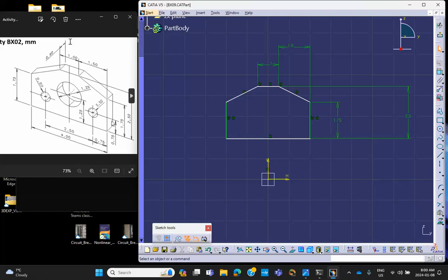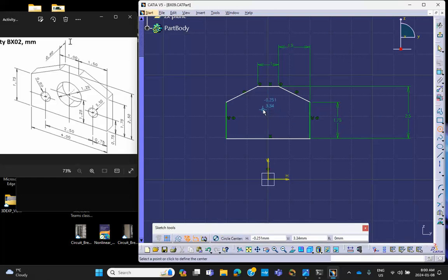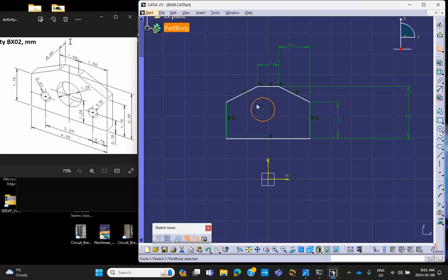So let's go ahead and select these, draw these circles. Let me do a circle here first of all. On purpose, I'm going to put it there. But then I want this to be on that vertical axis. So I select this point, control that line. I like to use this, but there are other ways of doing it. Let me show you another way. You say dimension between this and that. You can make it 0 or right click and say coincident. So this is an alternative way of dimensioning, making that coincidence.